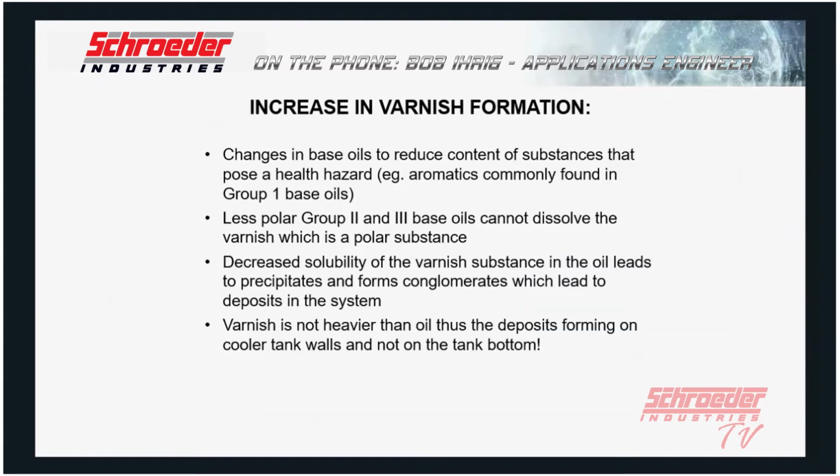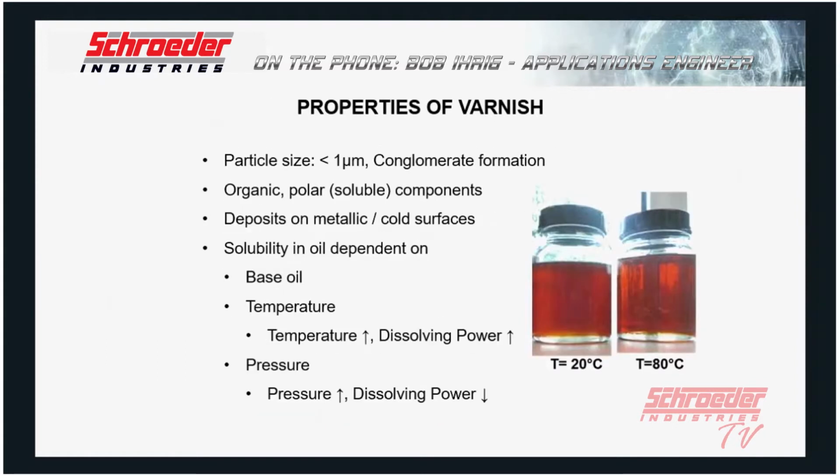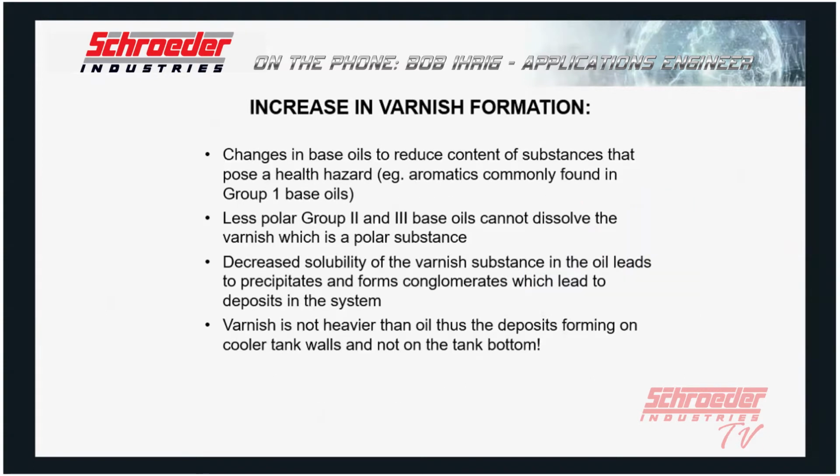So one of the items I mentioned was base oils. This is, I guess, part of the reason that we're hearing a lot more or getting a surge of varnish cases in recent years, because of the greater use of highly refined mineral and synthetic fluids. The more refined, the less polar or the less soluble and less conductive, which has its own set of influence on varnish formation and oil degradation.